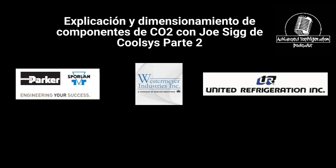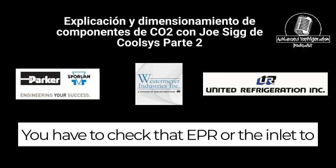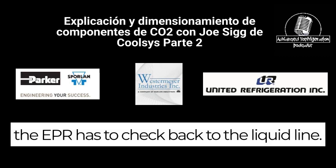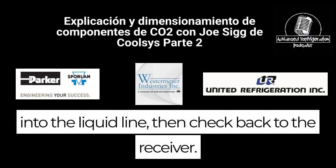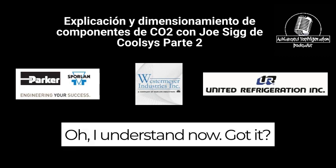So you have to check that the inlet to the EPR has to check back to the liquid line. That way, if it ever gets higher, it'll check back into the liquid line, then check back to the receiver. I understand now. Got it.